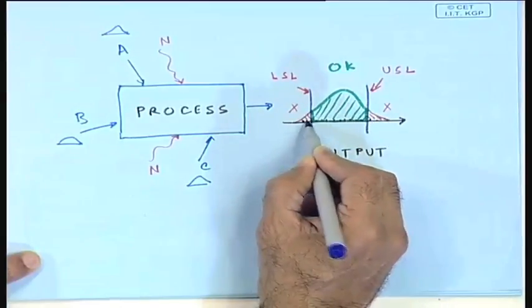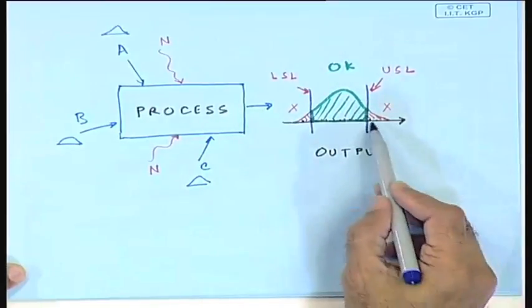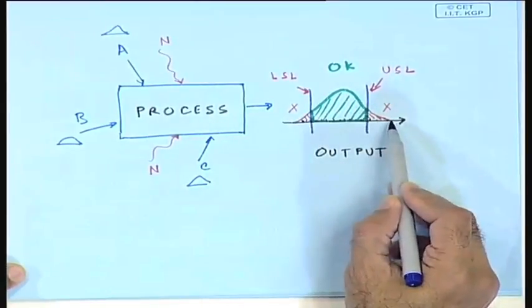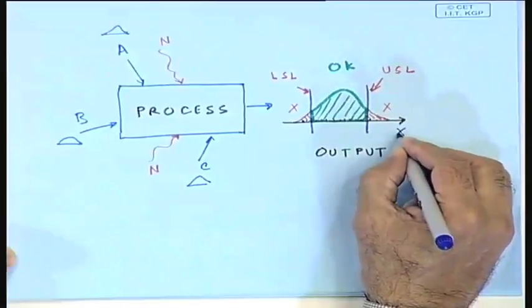And it turns out some of those are below the specification limit here on the lower side, and some are beyond the upper specification limit. But these are all individual measurements. I'm not talking about X bar. I'm not talking about R. I'm talking about raw X values. That's what I'm talking about. That's what I've plotted. In fact, that is the quantity that I need to measure in large quantities, large numbers, to try to see what the distribution looks like.